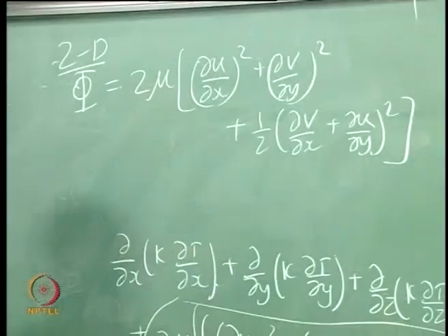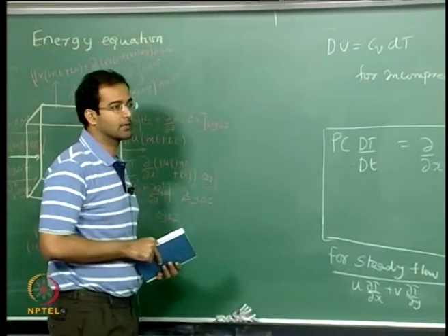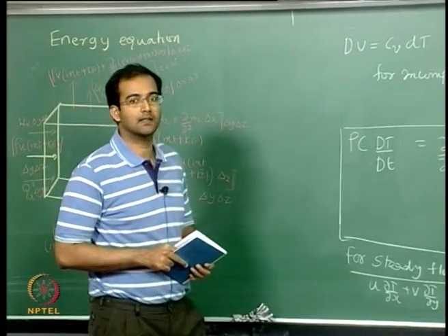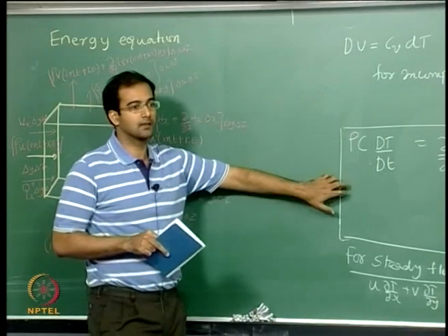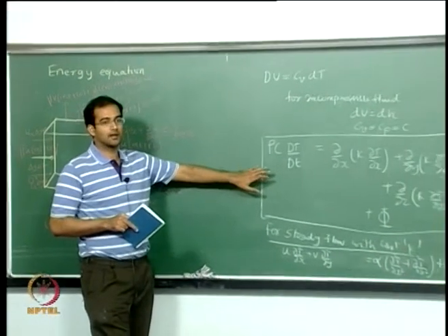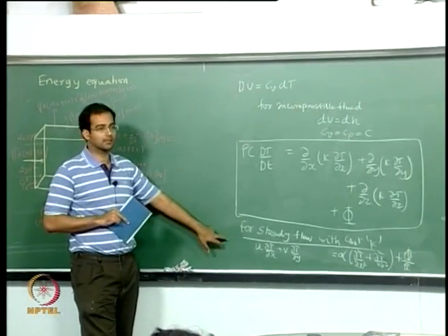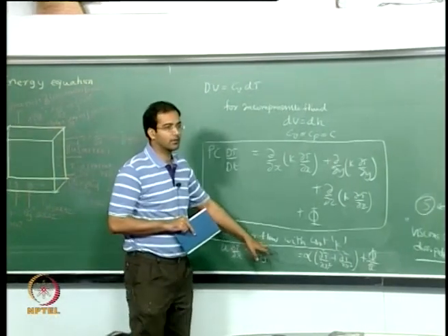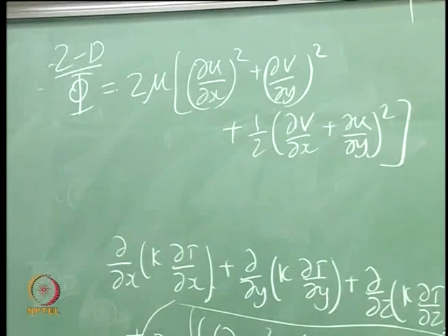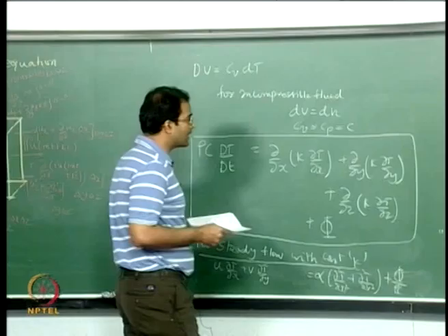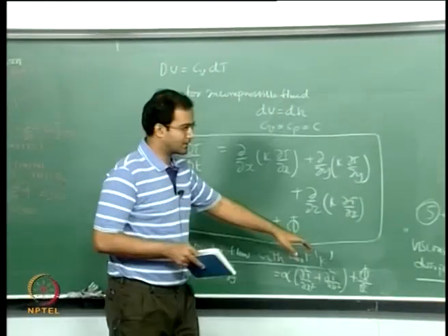Alright. So finally when we are working with the energy equation in this course for doing the analytical solutions, we will be looking at these approximations, okay, incompressible flow and mostly in 2-dimensional. We are concerned only with 2D flows for analytical solution. So this is the form that we are going to work, and you can see the viscous dissipation also gets substantially simplified.